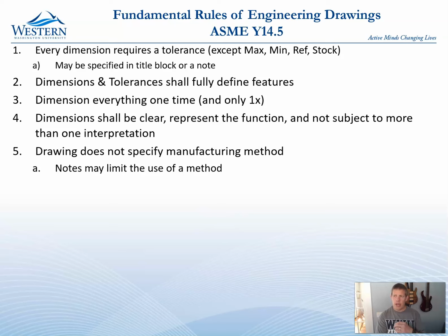There are other things. It might be a material incompatibility from the pre-process. So there might be the likelihood of a coolant or some residue that would not be allowable. Like if you're doing something that's going to go into vacuum, you might not be able to have some oils used on your part because it's too hard to clean those oils off before it goes into vacuum.